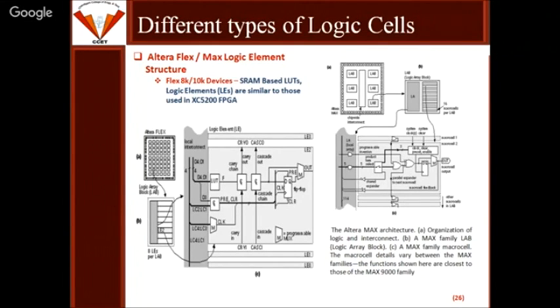Altera is using the FLEX or MAX logic element structure. It is an SRAM based, lookup table based architecture, and again SRAM is used as the logic element, and then we create the different designs.